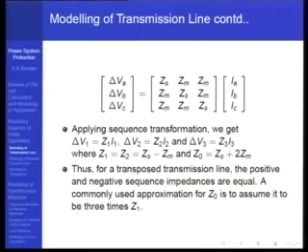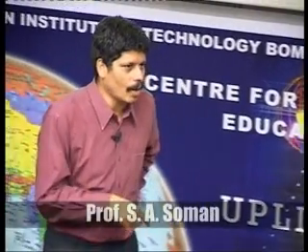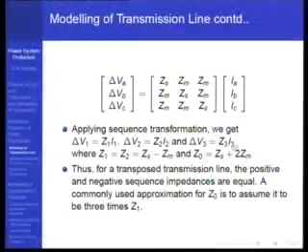So what we do is, whatever drop is going to take place in that ground return, we add it into this value here, Zs plus 2Zm. We add all that drop in the ground into this Zs plus 2Zm, and then calculate the Z0. Therefore, the calculation of Z0 is always based upon certain assumptions about what you consider your ground is.